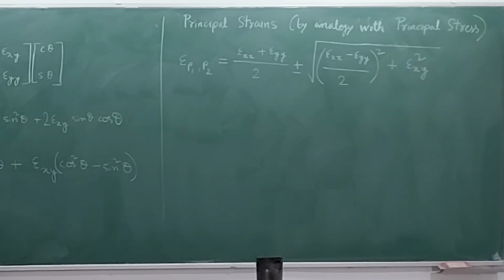Now if we cut this body on a certain plane, it may so turn out that on that plane the shear stresses are zero, and on such a plane whatever the normal stress is, we will call that the principal stress. This is the general notion.